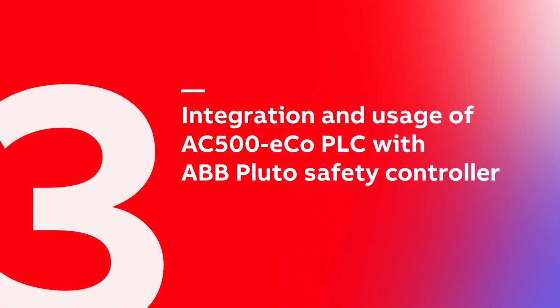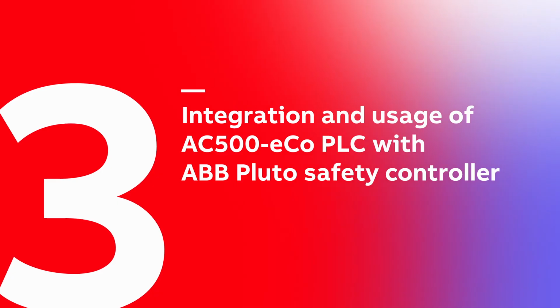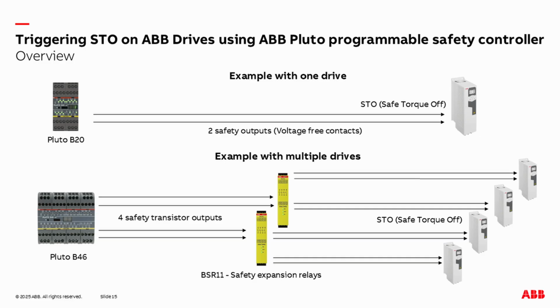And finally, how do you ensure safe torque off on a drive then? The most simple example is to simply utilize the 2 safe relay outputs of the Pluto B20, connect it directly and break the safe torque off in the drive. But what if you have an application with several drives? Yes, that we have an answer for, and you simply expand the safe output, the transistor or relay output, with an expansion relay, in this case a BSR11, and then you can break the safe torque off of multiple different drives.